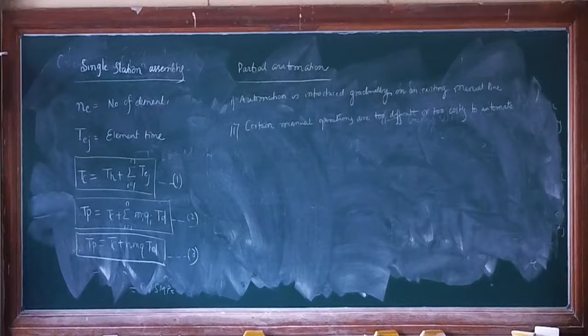Pi is the probability of a breakdown per cycle. With this equation we are taking the probability of breakdowns per cycle, how many breakdowns happen in that particular line. To perform the assembly operations, we take Qi and Mi: the fraction defect, and the probability that a defective component will cause the station to jam. We take Mi and Qi as equal. So the defect rate and the probability that the defect will cause station i to stop; that will stop that station.